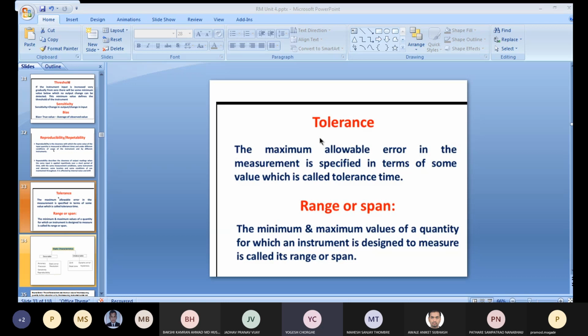Correct. And the least material condition and maximum material condition, these two types of tolerance are very important, which are able to lower the cost of the product, the machine cost. This tolerance will give liberty to the operator to machine the component. Good one. So this is very important.